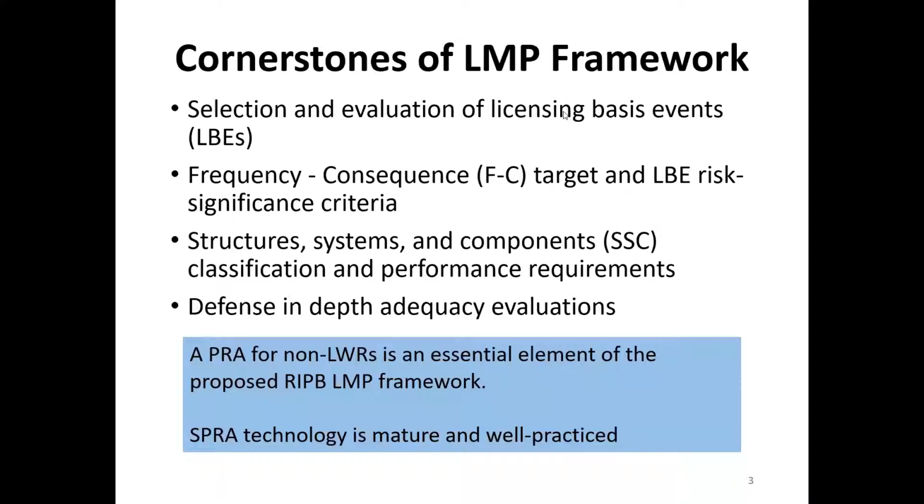In the LMP framework, the PRAs are supposed to be conducted for all the initiators and all the plant conditions. And as we go towards these new designs, which are passive and inherently safer, the external hazard, particularly seismic, becomes an important factor because of its uniqueness, its ability to affect the entire plant, both prevention and mitigation, and all systems, structures, and components. Luckily, seismic PRA technology is mature and well practiced and can easily be integrated into that framework. And you will see how the seismic PRA is going to play a major part moving forward in the seismic design.